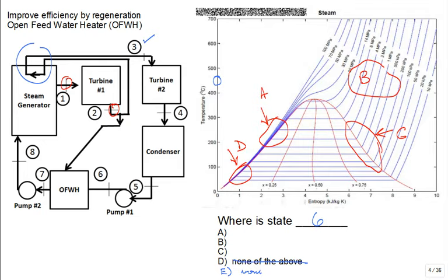How is it that the second pump has such a huge pressure boost compared to the first pump? Well, those are the numbers I threw out. You could go from 20 kilopascal to 2 megapascal, and then from 2 to 8. You could go from 40 kilopascal to 4 megapascal, and then 4 megapascal to 8. But if you go too high a pressure, let's say it falls from 8 to 4 megapascal, that first turbine is not going to look so good. I mean, come on, we want to get it down.